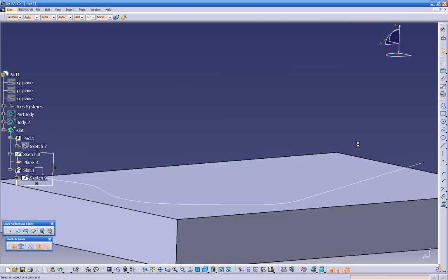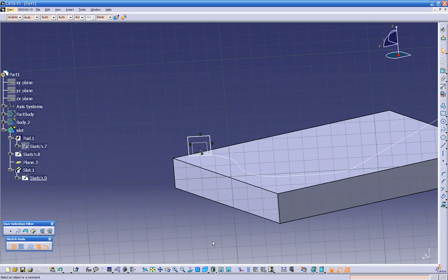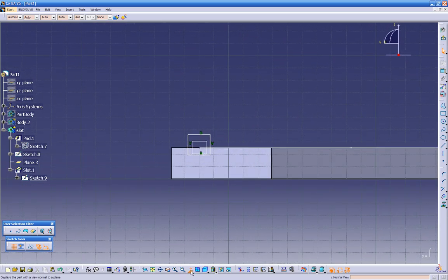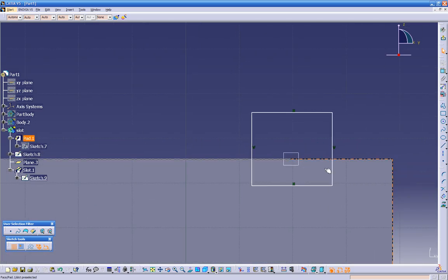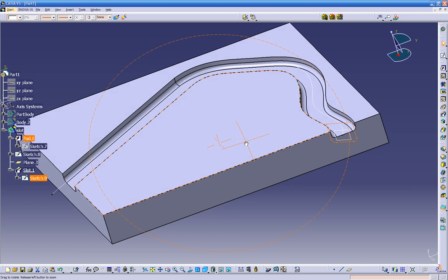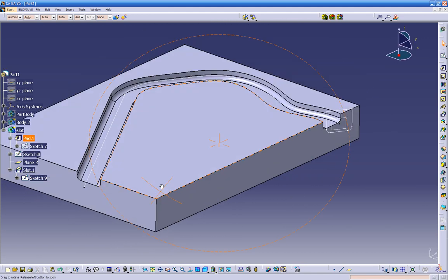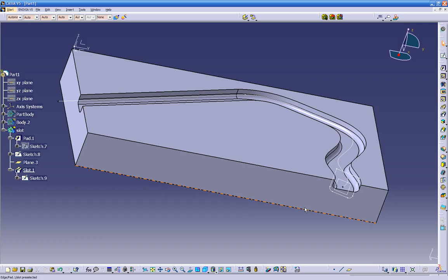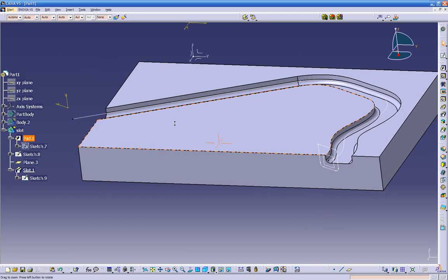We can double click on our sketch, go back on our sketch, let's click normal to view twice, and we can have our radius over here, and we can just highlight this, click corner radius, 0.100, and get out of here, and we have our fillets in there. So whatever is easier for you, just use it. You know, there's a couple ways of doing the same thing with Catia. It's totally up to you.